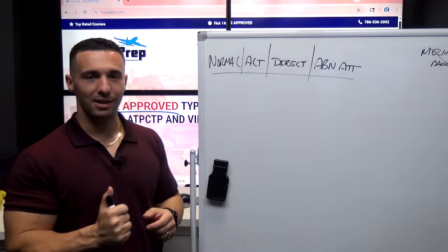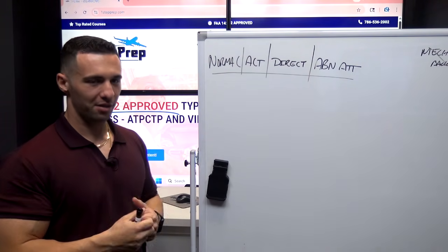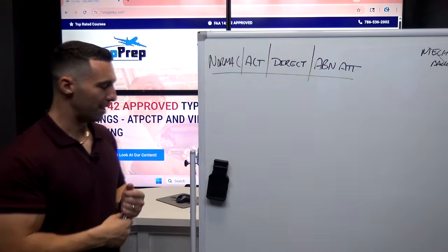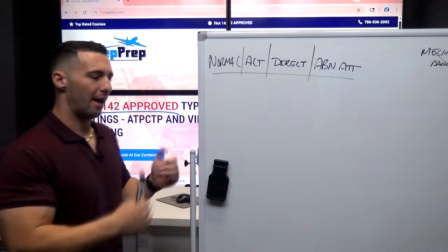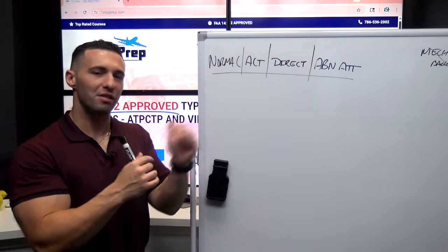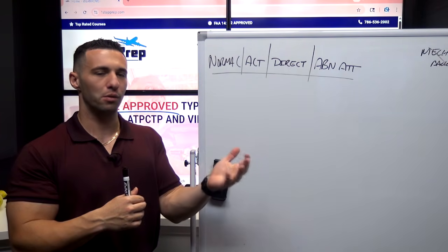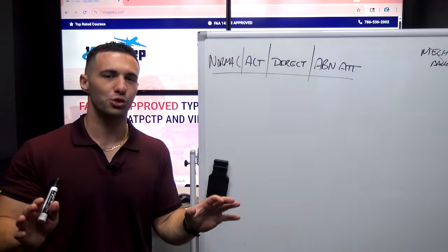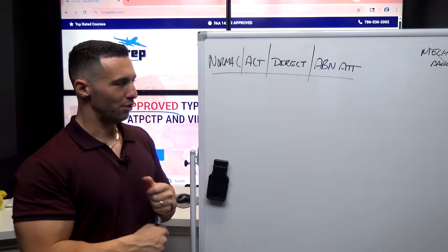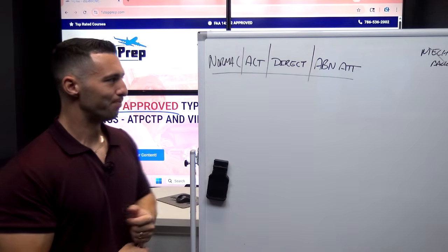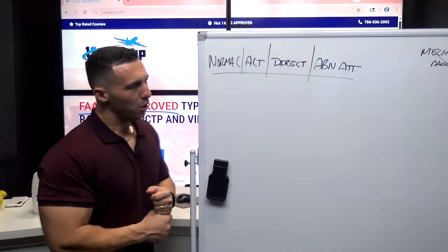want to grab the side stick and yank a ton of G's on this, especially if I have a lot of airspeed. But we definitely have the VMO at a value that has a considerable buffer, and we can actually safely overspeed more than that in a very extreme, what's the word they use, egregious situation. So that's abnormal attitude law.